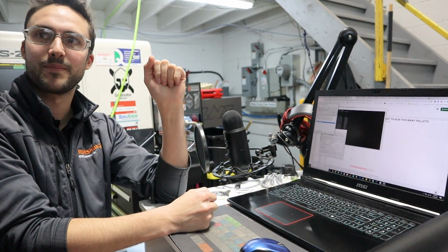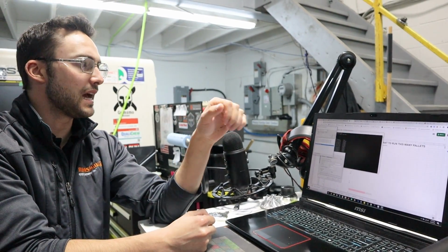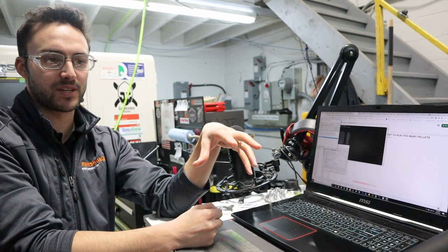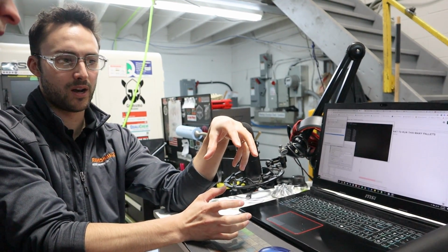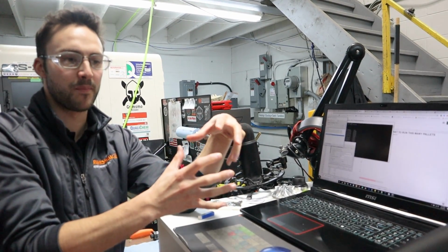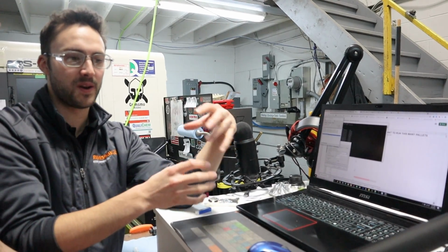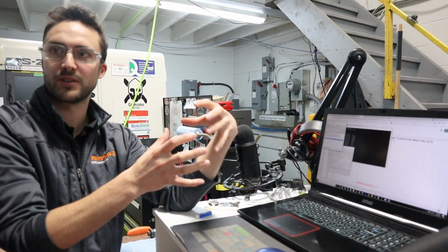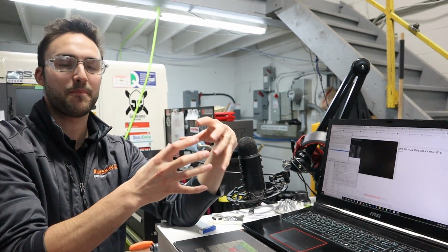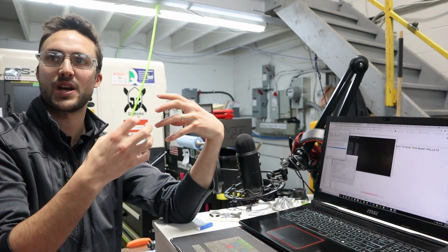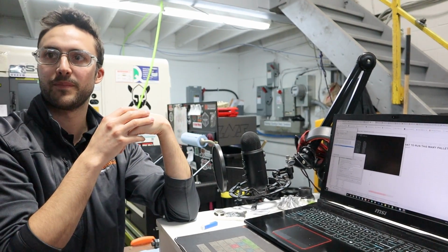Okay. In the router, you just need to add permissions or add a... Yeah, you just need to make sure that, in particular with the Fanuc, the port number that it's uses is 8193. That is for the FOCAS system that it uses, okay? That port needs to be open, an open channel, for all of this to communicate.